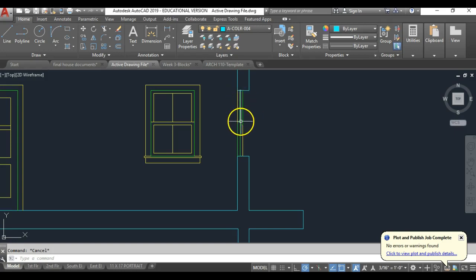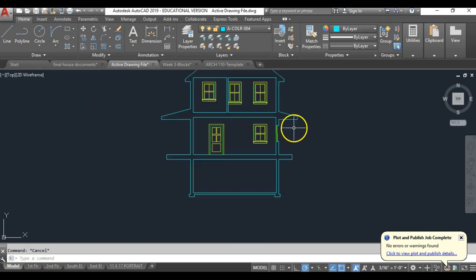And so even though I'm technically cutting through here, by lowering the line weight of this cut window, I will make this read as an opening as it sort of feels. And it's exactly like in plan why we do that. In plan we have the walls as being cyan and the windows as being lighter line weights to sort of, again, give that effect that, hey, this is an opening in a wall that you can physically see or look through in this case. So that's how you do that window.